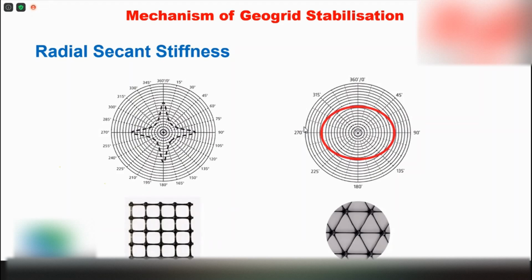Just as I said earlier, the production for this geogrid is all from a continuous sheet of membrane. In this case, the triax is a polypropylene membrane, which comes as a continuous sheet. It's produced by punching holes and then stretching in a certain manner and with a certain strength to produce the grid. So it's a very strong and continuous grid. And this grid of triangular pattern comes in different sizes to suit different types of loading.